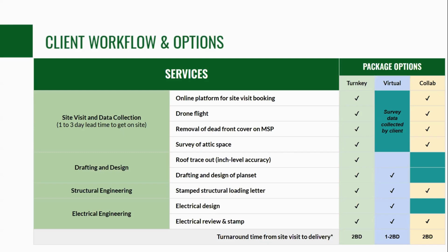They will always do a drone-based roof survey, to get some really nice, accurate, granular rooftop data, which again can feed into the Enact platform. We will collect any structural or electrical measurements on site, pulling the cover off the electrical panel and getting a nice folder full of photos. If you opt for the turnkey package, which includes design and engineering, we'll take it the rest of the way through permit.